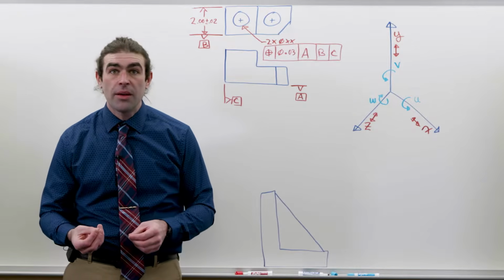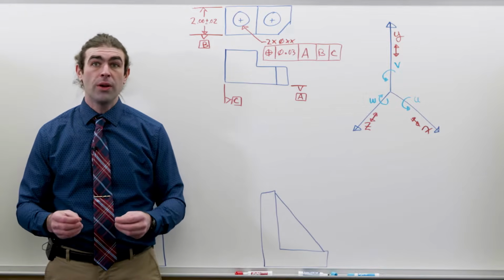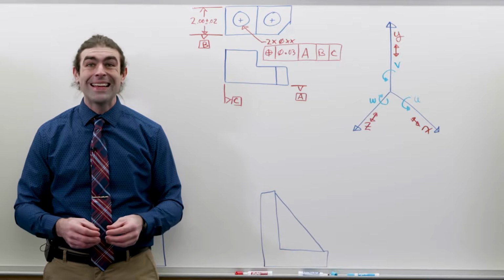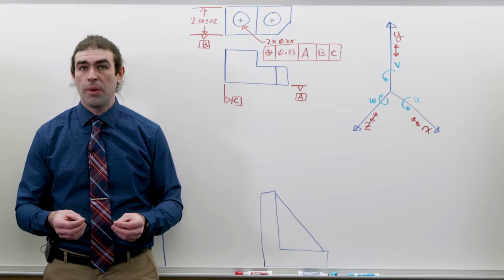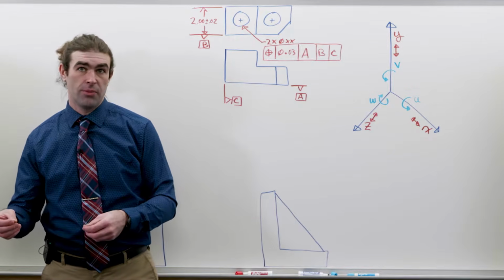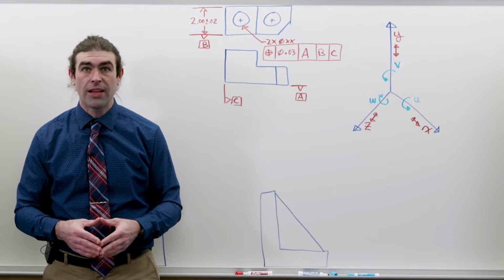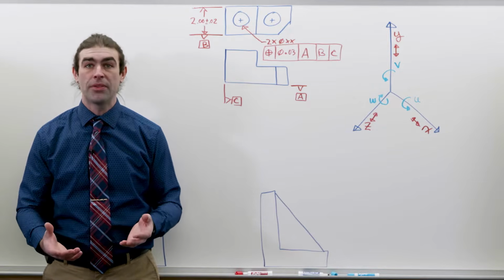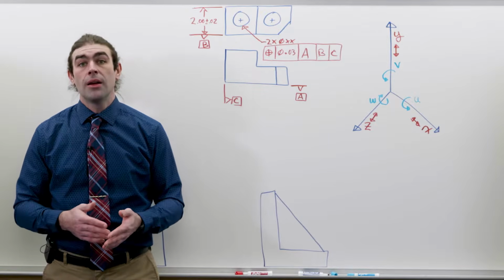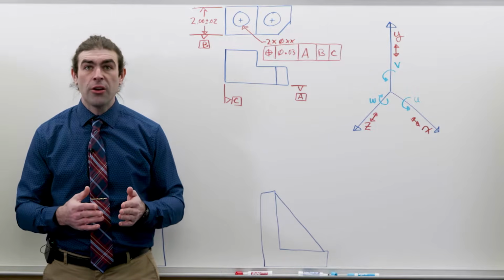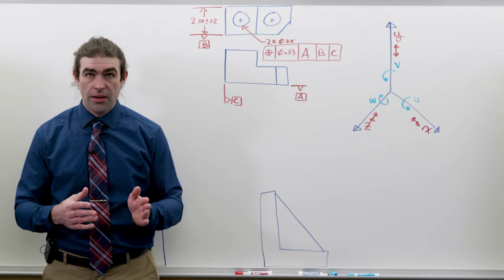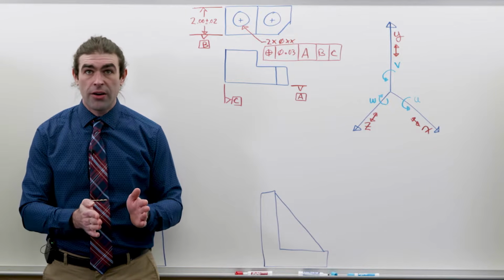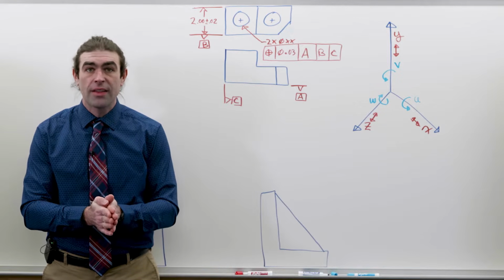The next concept I want to talk about is true geometric counterpart. This is kind of like actual mating envelope, but for datums. So the true geometric counterpart is a perfect shape that's the opposite of the datum. So if your datum is a flat plane on the part, the datum simulator is a perfect flat plane that touches it.